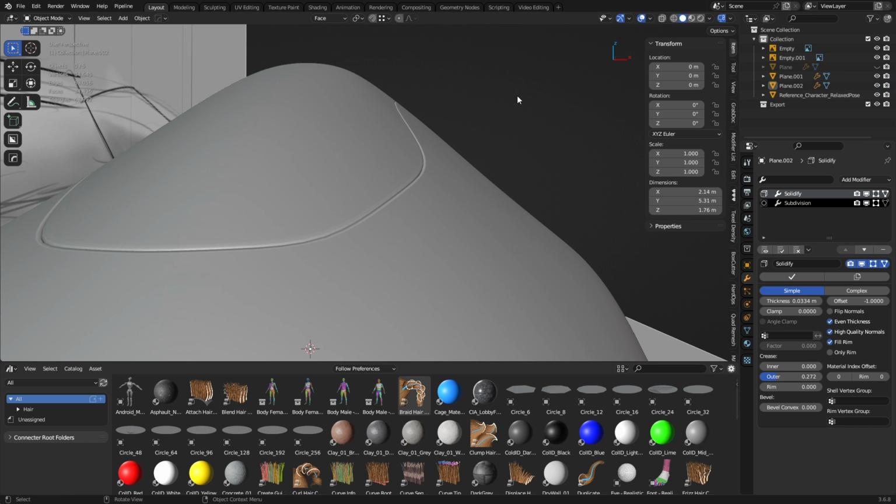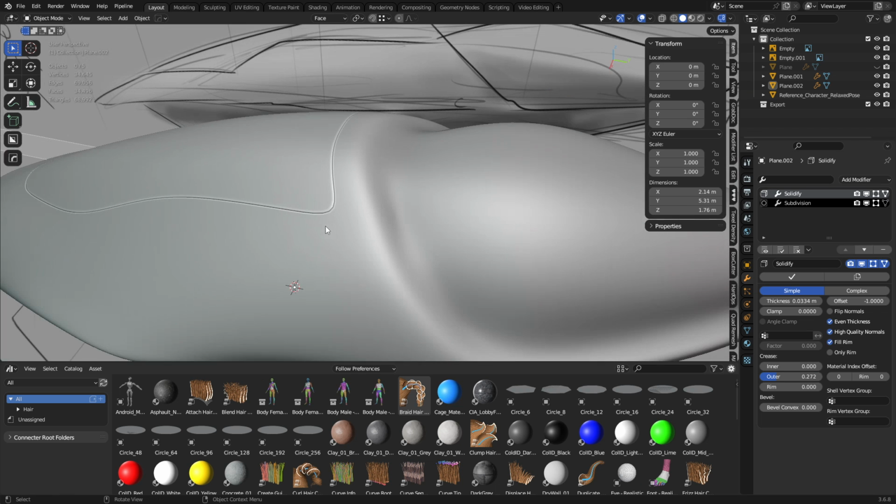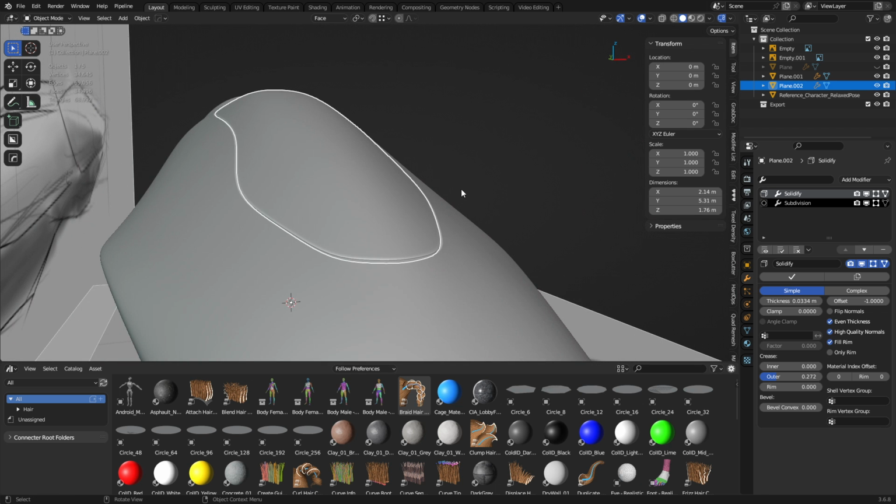So that's nice to know, right? Unfortunately, if you have sharp edges, like sharp angled corners, you're going to have to manually model those. There's a lot of ways you can deal with them, sort of. You can try to use creases, you can try to use inners and outers and bevels. A lot of times just going destructive tends to work out the best, so just keep that in mind.